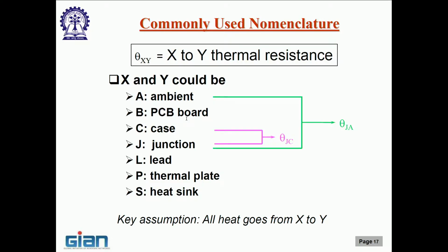It's sometimes difficult to measure internally, but many times with thermal test vehicles, some of the damaged ones that Intel let me take away when I left the US, these typically have a power map inside, not much circuitry, typically heaters, and some temperature sensors to measure the temperature in the silicon at the places where the heat flux is maximum. Because at the end of the day, when I say that my CPU die cannot exceed 100 degrees, I am really talking about the maximum temperature at the junction. And I will come to that.